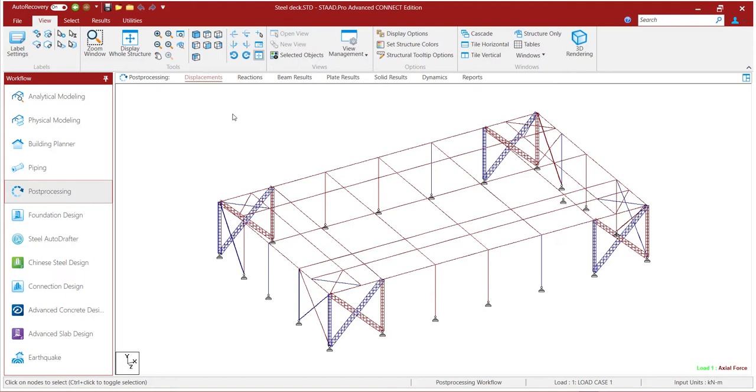Every diaphragm has some finite in-plane stiffness. For example, in this case, if your diaphragm is not meant to be a rigid diaphragm and you have created all those horizontal cross bracings just to resist lateral deformation, then the purpose of these cross bracings is defeated by the introduction of this rigid floor diaphragm, because here these cross bracings have not carried any proportion of the actual forces, so they have no role here. So there is absolutely no point in adding those cross bracings if you are assigning the rigid floor diaphragm.